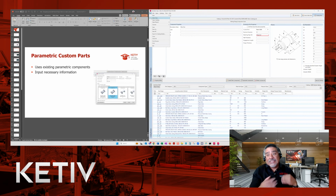So this is the easiest part because, like I said, these are all predefined. There's scripting logic between the spec editor and Plant 3D that's involved in creating these components already. So all you have to do is fill in the size parameters, add the information, and then you're good to go with the part within the model and everything. So that's kind of the way to go if you can go that way, because that's the easier way.